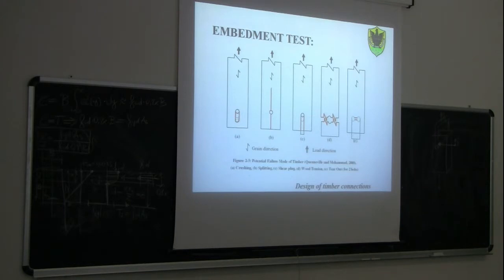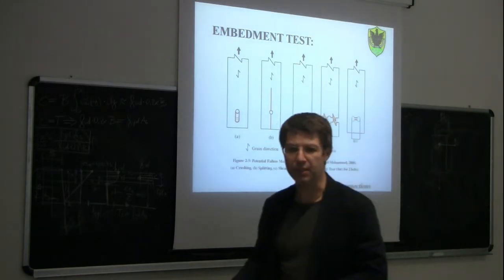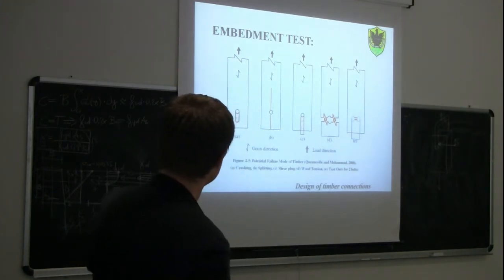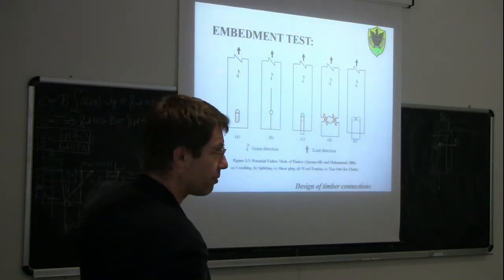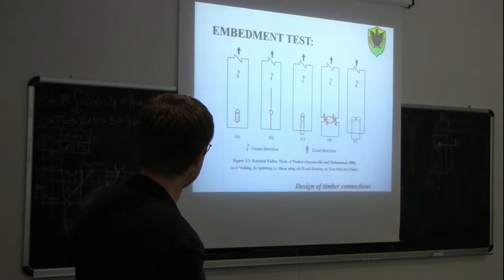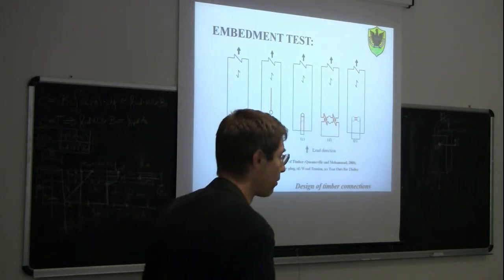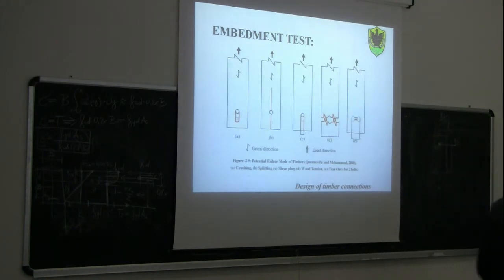The dowel compresses the wood at the interface, and for this reason the initial hole elongates due to the crushing, the plasticization of the wood at the interface with the dowel. This kind of failure, the crushing of wood, is called embedment. Embedment means la rottura per rifollamento.